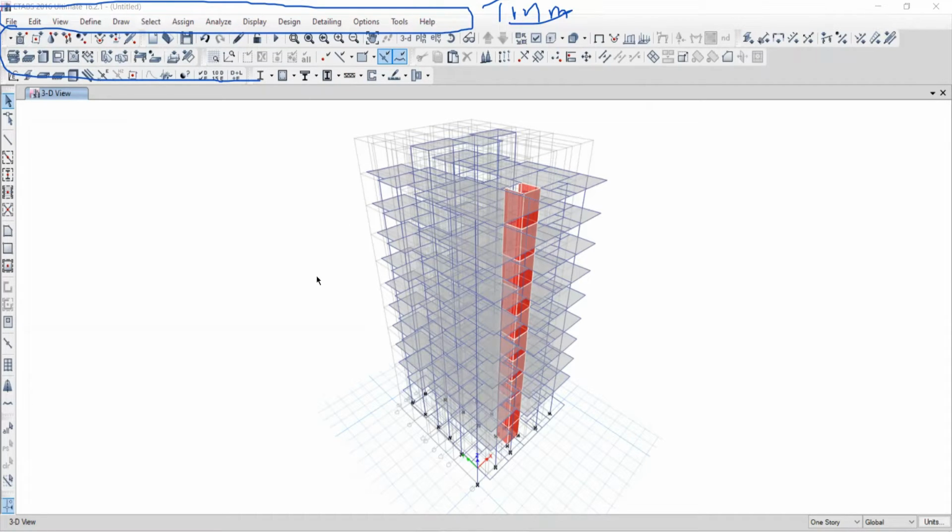But you might have the experience of using CAD software. In CAD software, we have the shortcut keys: L enter for line, C enter for circle, a trim command TR enter, and offset. So those are the shortcuts.